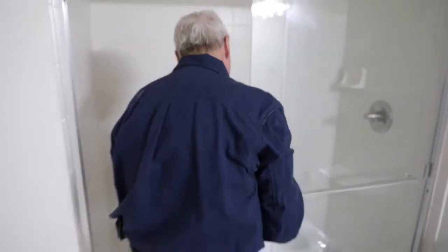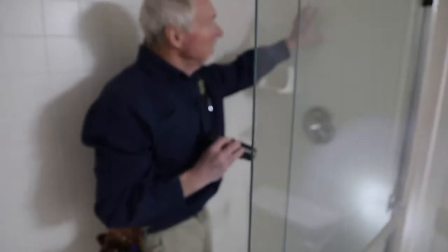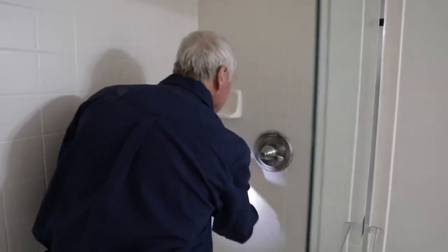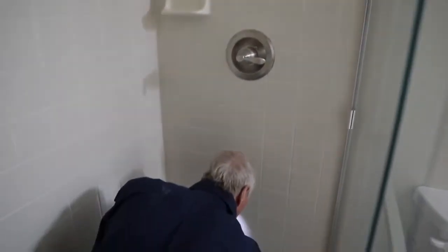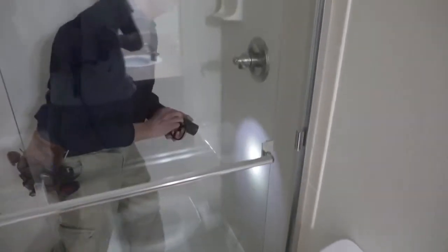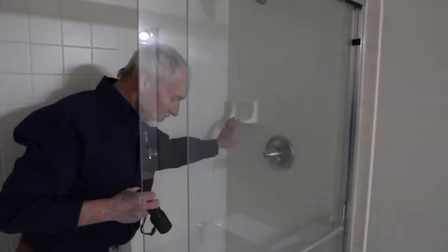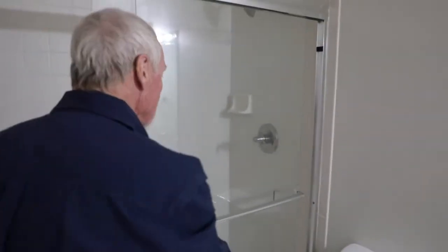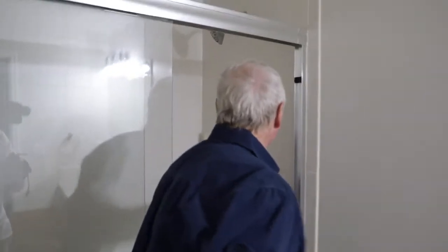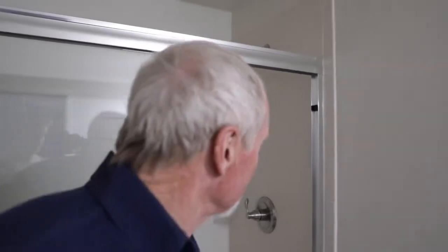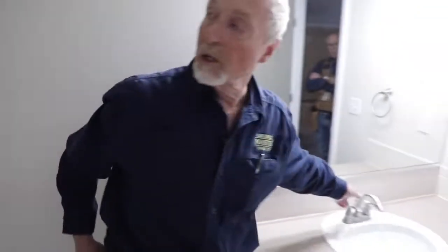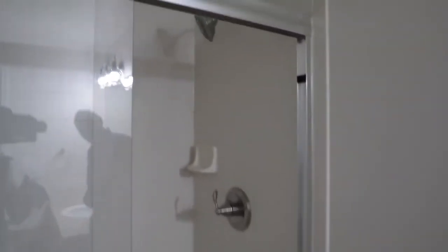Then I'm looking for voids in my grout or any issues with that. And then something I like to do, particularly on the handle side, tap on the tile around it. If you hear clicking, it indicates that the tile are loose. A solid thud like we have here is a good sign that they're properly attached. So that's good. We have our sink running, so it's a good time to run our shower here. Have decent pressure, but we'll turn off our sink and see if we get a major change here. Just slightly, so that looks pretty good.